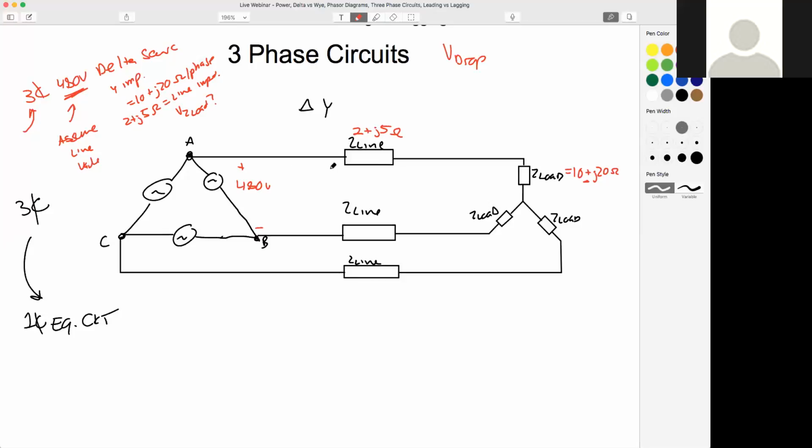All right, what's the first thing we want to do? And essentially, what value is missing in this circuit to know the load? In other words, if I combine just one more variable with what we already know, we would be able to find this voltage drop. What variable would that be? And what is my first step I would have to take to solve this problem? Who can tell me? Good, current. Everyone's saying current. Great. Yes, exactly, right? Ohm's law, V equals IZ. So if we knew that current, we already know the voltage, we know the impedance.